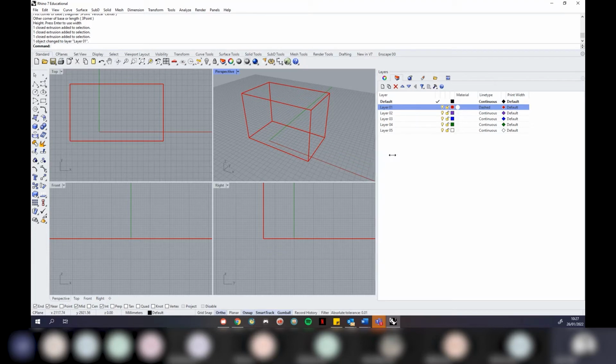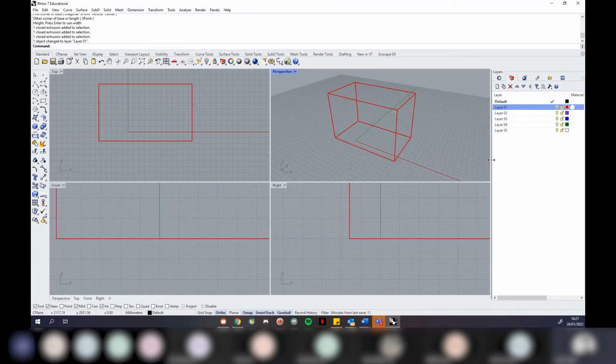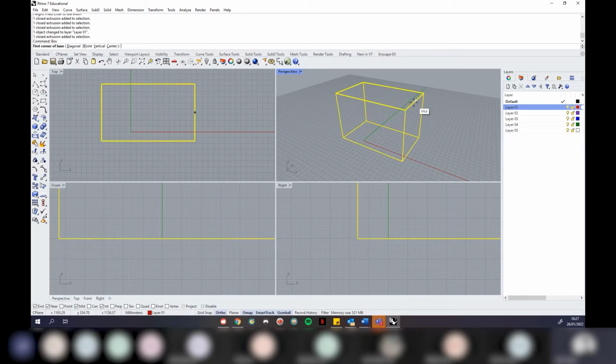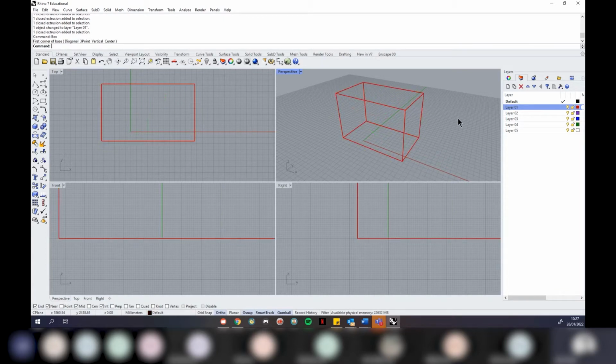So I think it's relatively straightforward. Again, if you're coming from another software such as AutoCAD, you should be familiar with this. It's the exact same kind of system. But if not, it's just something you need to play around with. If you're on a Mac, by the way, if you can't right click and choose change to layer, I believe you can select your object, right click there, and choose move to layer, if I remember right. If not, I think they have changed it now, but if you're using an older version, you might just need to right click the object to change that on a Mac.